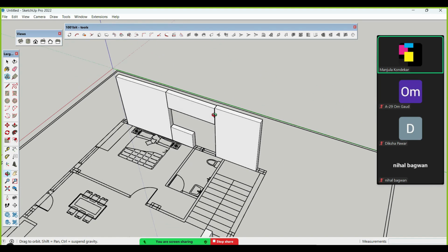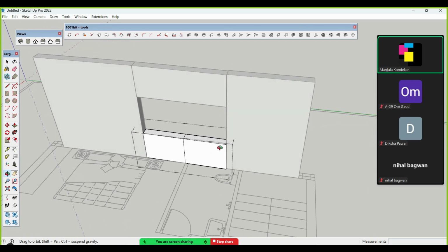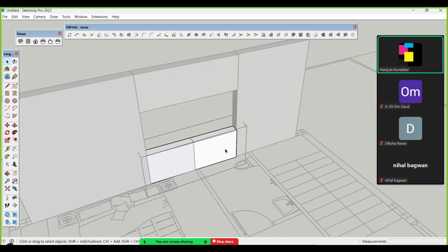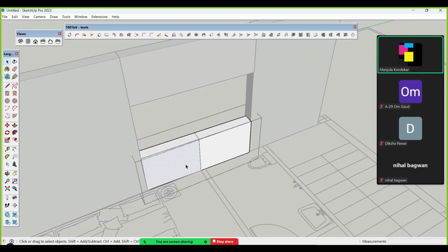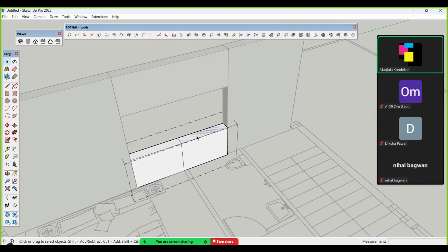And then even you can edit this. That is 3 feet. But this time I just take a control and push. Because I wanted to divide. Why did I want to divide? Because this is the bathroom and this is the bedroom. For the bedroom I had given 3 feet sill height, but for the bathroom I have to give 5 feet and more. So extra 2 feet 6 inch like this.